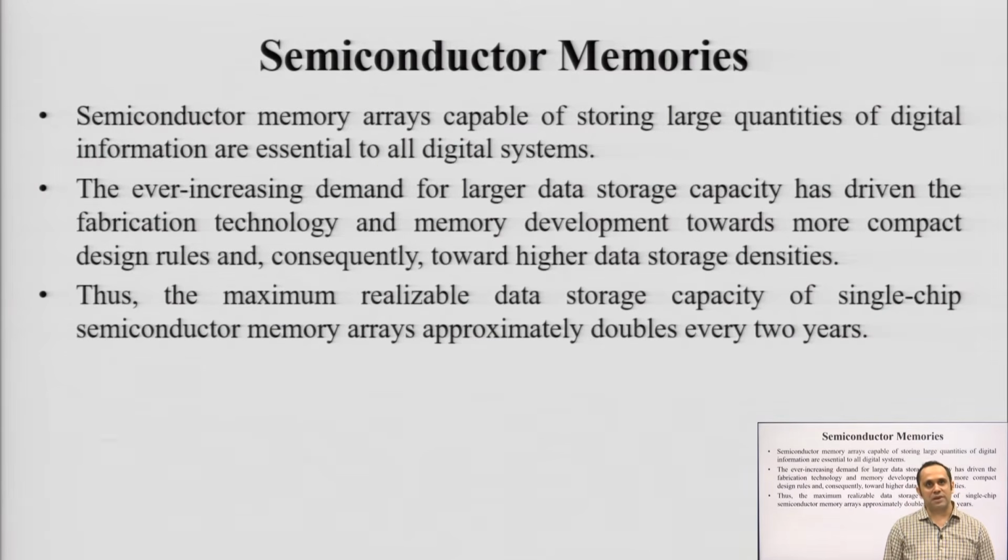Okay. So, every memory structure, memory circuit or memory element will have two things. One is the address of that memory, where the data is located or has to be updated. Second, the data itself. Okay. These two things are also used interchangeably with notations like word line and bit line. Okay. The level of memory requirement we have these days can't be implemented by a simple block of memory. You would need what is known as an array of memory.